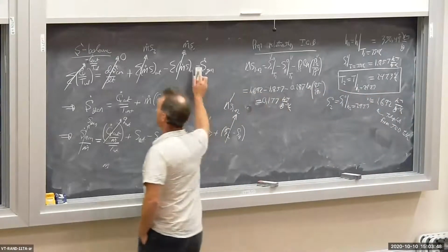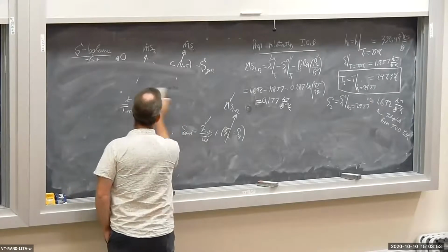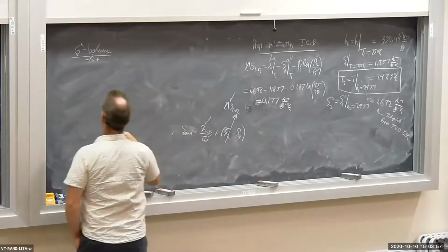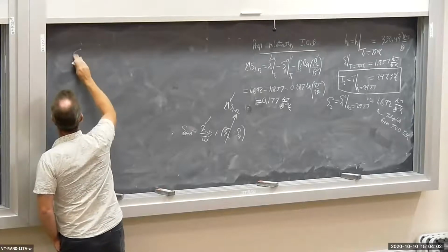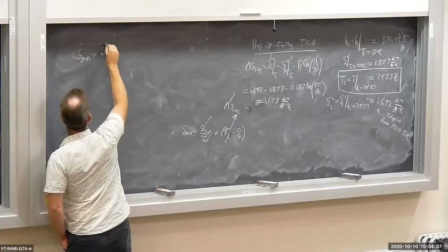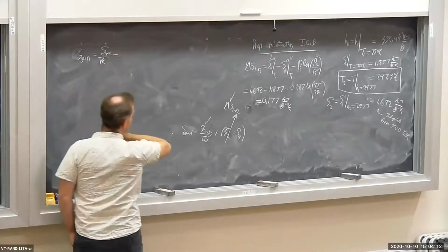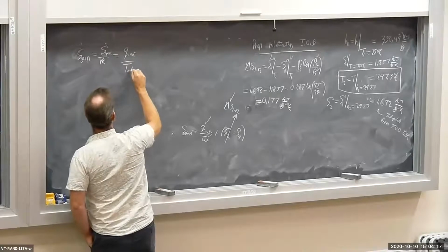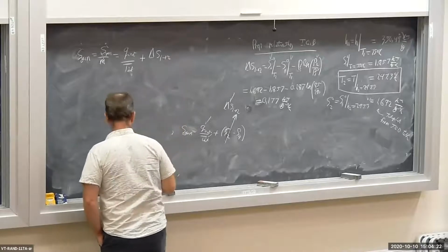Okay, I'm running out of room here. I'm just going to immediately switch up to the top here, rewrite my equation for S gen, and we're going to crank out what S gen is. So lowercase s gen, which is S dot generated per unit mass flow. So that's Q out over the interaction temperature plus delta S from 1 to 2. We have everything now.